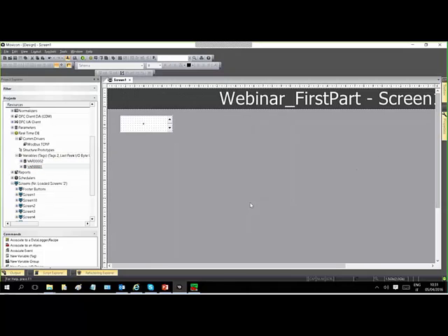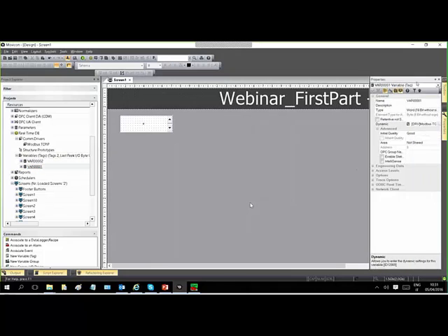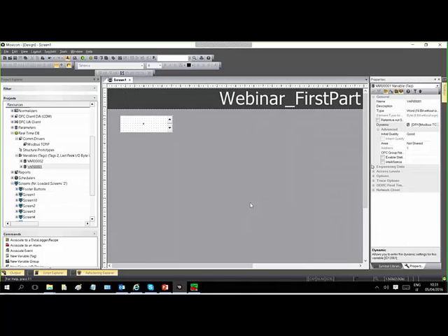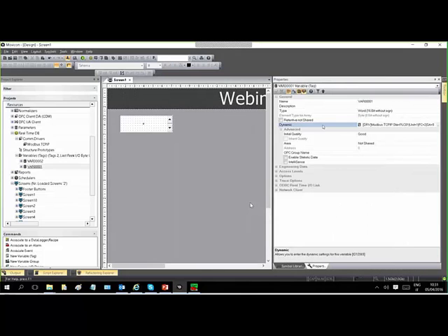We were looking at the variable properties. This is the important part of a variable, the dynamic property of the variable. Now, the initial quality is good. The quality will be updated according to the communication state. If you lose the communication, the quality of the variable will go bad. Some advanced properties for the statistic, to define an OPC group, to define and use an internal area, or to define the array area.